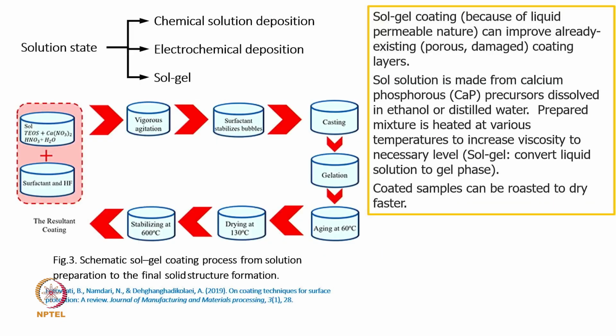In the same category, we have a sol gel. In this solution, sol gel, basically we make a solution, and then in the initial, very elementary steps, we need to agitate it in a manner, then we need to think about the surfactant, so that whatever we are mixing does not get settled down and remains in a floating condition, and then we go ahead with different types of exposure. So, to some extent the liquid phase comes down and the gel formation starts.